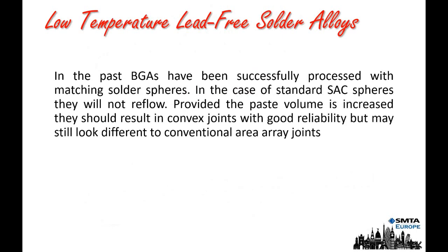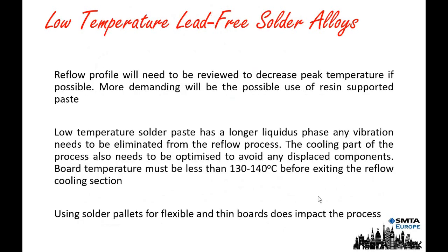In the past, what we've seen really is the use of low temperature materials for the repair and rework of area array packages. The reason is to make a reliable solder joint as a repair on a product and minimize the possibility of damage to other adjacent components. Because if you're replacing a part, you want to eliminate the possibility of secondary reflow, which can occur, and I know from my own experience it does occur. And Indium have been great exponents in promoting that technology in terms of rework and repair, with excellent presentations from Ning-Cheng Lee in the past.